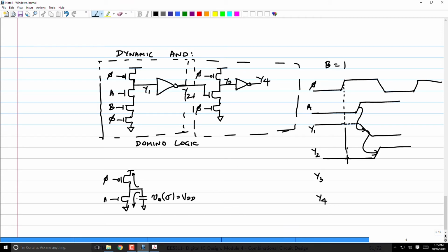Yeah. Correct. So you're right. If it goes below VIH, it's a problem. However, generally at the speeds that we operate at, the clock is not going to be very, very slow. It can't be 1 Hertz. 1 Hertz is such a limiting case that I gave as an example.